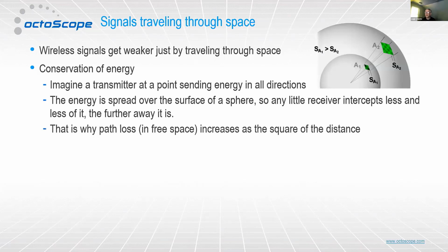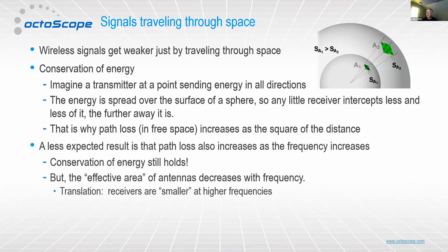That's the basic principle of free space path loss. And that one's kind of easy to understand because of that model that I just described. If you just think about stuff going out in a sphere, that's how it works. There's another one, though, that, once you understand path losses, becomes a basic thing that you always think about, which is that the path loss also increases with the frequency. That one I think is actually less obvious, and it's part of the reason I wanted to do this slide, just to make sure that everyone understands why that is as well.